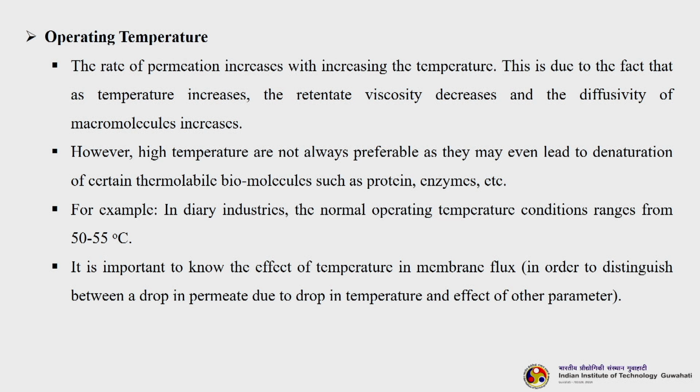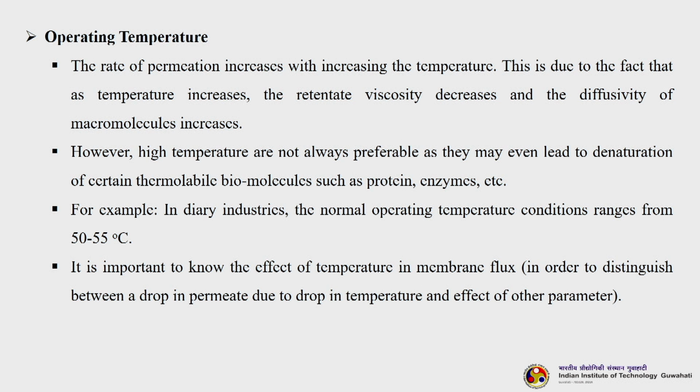The next parameter is operating temperature. Temperature does not necessarily play an important role in all sorts of ultrafiltration applications. However, wherever there is a temperature driven separation process, of course, it will play a big role. Usually it has been seen that the rate of permeation increases with increasing temperature. This is due to the fact that as temperature increases, the retentate viscosity decreases and the diffusivity of macromolecules increases.